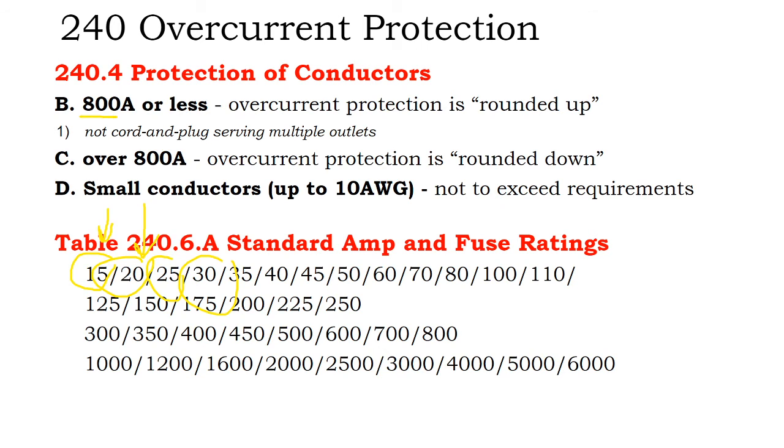Well, it's saying for breakers under 800 amps, you just round up to the nearest size. There's so much selection for breaker sizing at the small level that you can just find the next size breaker up and be fine. If you need a 30 amp breaker, you can't use a 40 amp breaker, or you shouldn't. But you're allowed to round up to the next breaker size, and it tells you what breaker sizes there are. Sometimes not all these sizes can be found at Home Depot. They might need some advanced ordering if you're doing something odd.